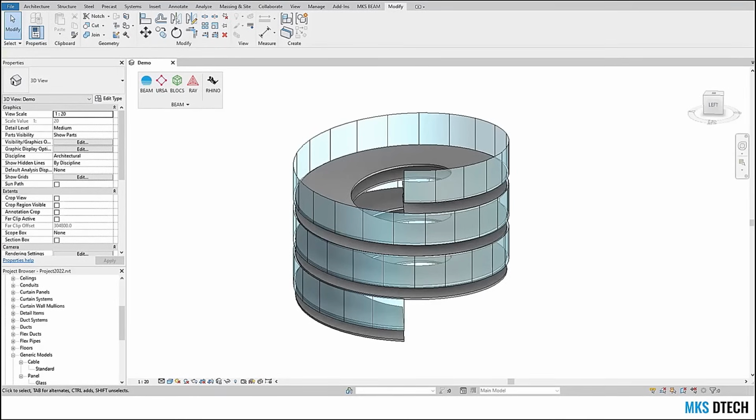Okay. So no, it doesn't work with shafts because shafts don't cut families. And because that is a loadable family that is not cut by the shaft. So you need to pre-cut the geometry in that case, or create a standard floor that will have the limitations we know about. The next is from Robert. No, I mean, Stephanie, is that clear? Yeah, that's clear. Thank you.